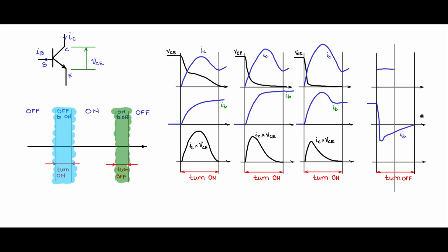Now this is base current, and now if you look at the collector current, you see that it stays almost unchanged till this vertical line that I have drawn, and then it starts to decrease and go to 0 into the off state. So this period where nothing much happens in the collector current or even in the collector to emitter voltage is called the storage period. It is called the storage period because most of the base charge is in the process of getting removed.